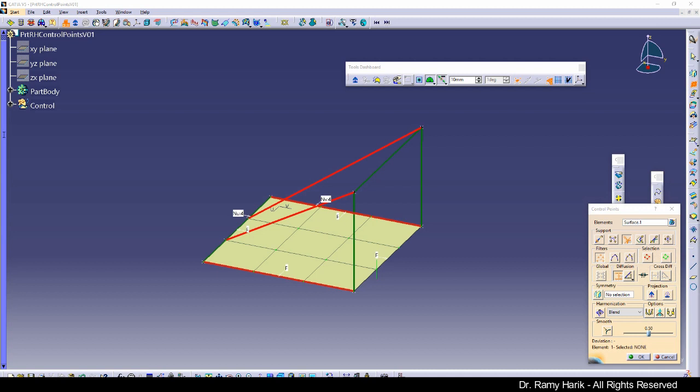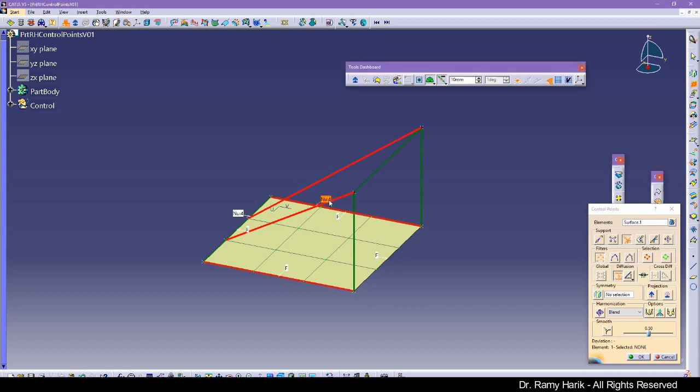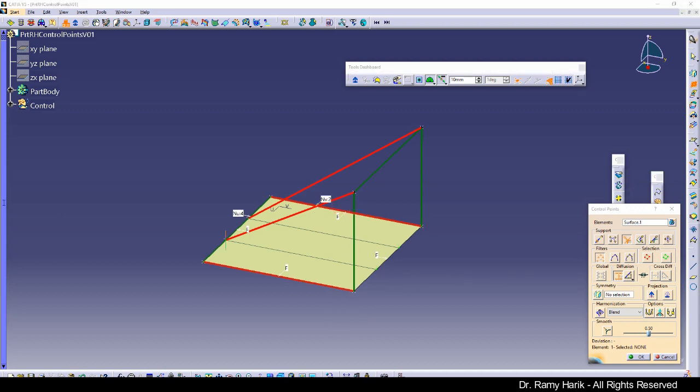So what we have is, and this is important to know, a contouring polygon that has from one side V equal to 2, and from the other side U equal to 4. So this is what it means. 1, 2, 3, 4. So you're controlling along 4 lines. But in here it's only linear. So you cannot have NV equal to 4. So we're going to right click on this one and select 2, which means now we are controlling it with respect to only these 2 points.